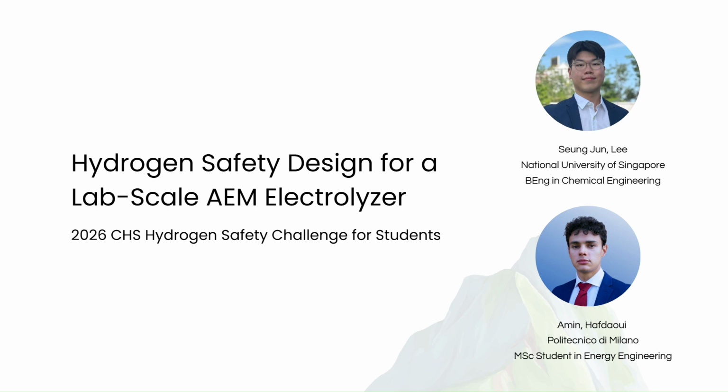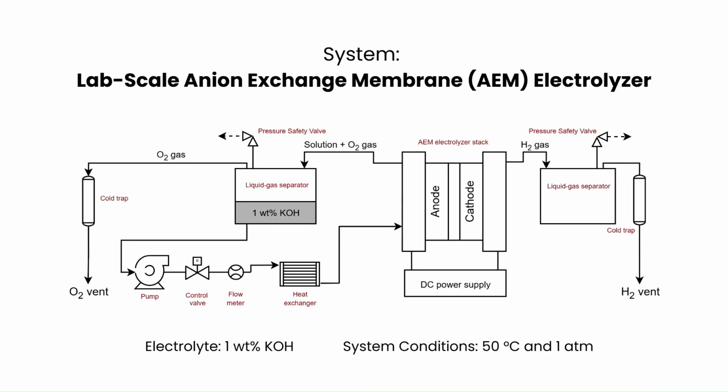Hello everyone, I'm Seung. This presentation summarizes our team's hydrogen safety design for a lab-scale AEM electrolyzer. Our system uses a 1 weight percent KOH electrolyte and operates at 50 degrees C and atmospheric pressure. Today, we'll analyze the main hazards, identify mitigation strategies, and show how a real incident helped refine our final safety